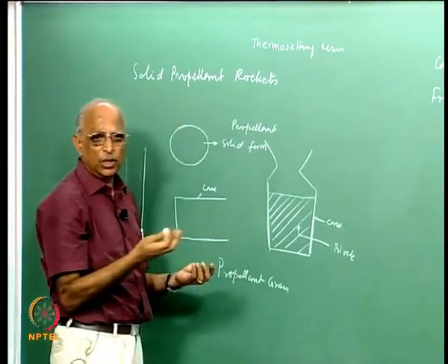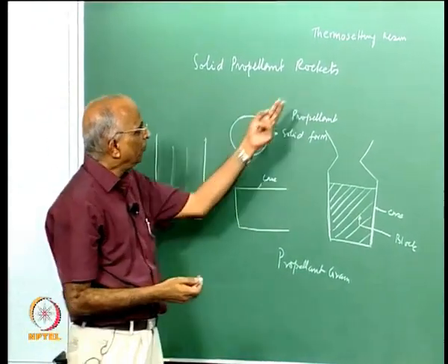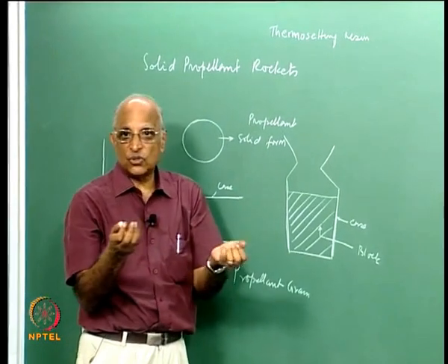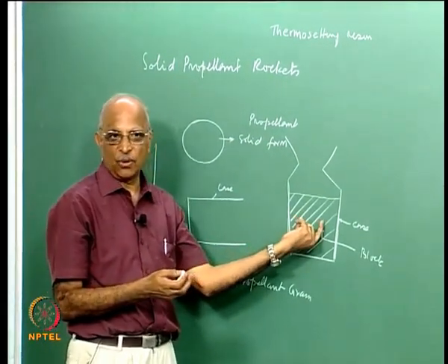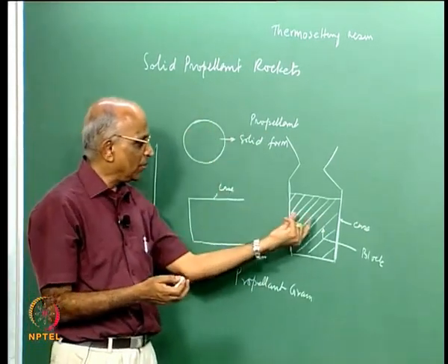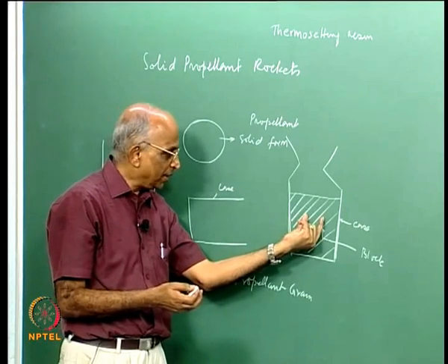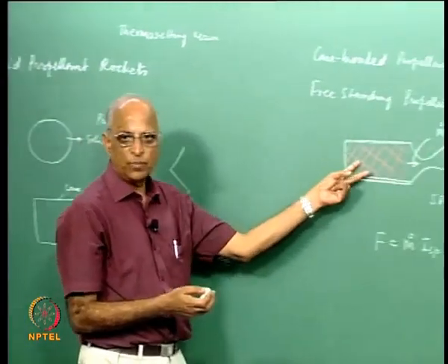Resin is nothing but a polymer, polybutadiene, like glue. I will show you some example. If you have plastic, which is also a resin, when I heat it, it softens. Therefore, we cannot use such resins for composite propellants, and the same thing is true when I use nitrocellulose and nitroglycerin. I make it as a liquid, I cure it, I make it as a block, and this block is known as a propellant grain.